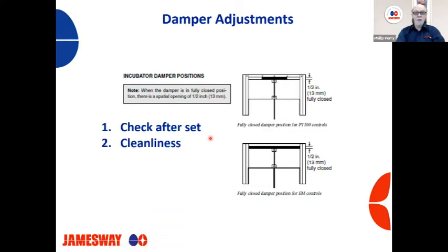The cleanliness affects this pressure. On our exit end, which is normally where we have more debris and dirt, if you fog machines, sometimes they can get real gummy here. This dirt buildup can cause this machine to actually be more closed here and cause a lower value, or excuse me, a higher value here compared to our entrance in.